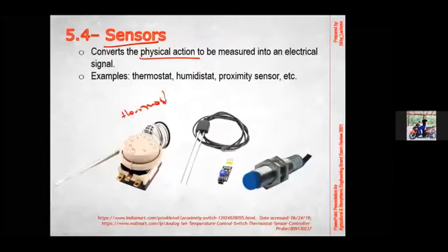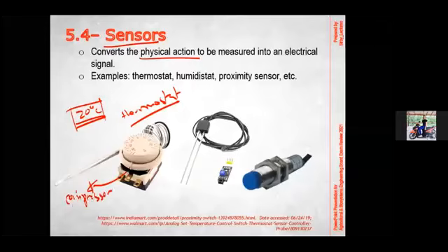This is a control device that senses, for example, if your thermostat setting is 20 degrees C, once it reaches above this temperature, for example 25 degrees C, then it will actuate, or it will send an electrical signal to, let's say, the compressors, so that the refrigerant will cycle in the components, for refrigeration systems or air conditioning systems, or things like that.